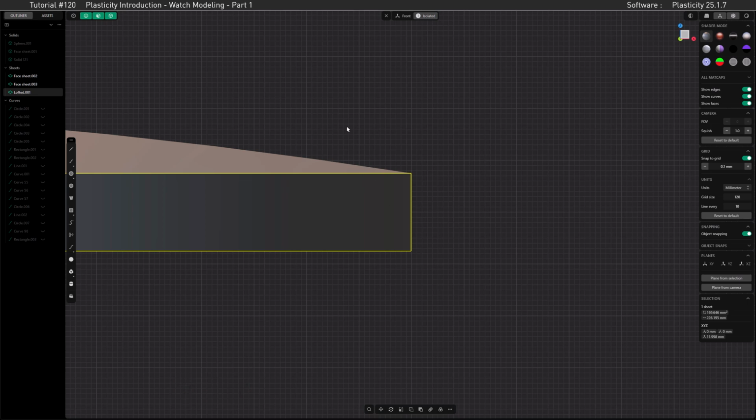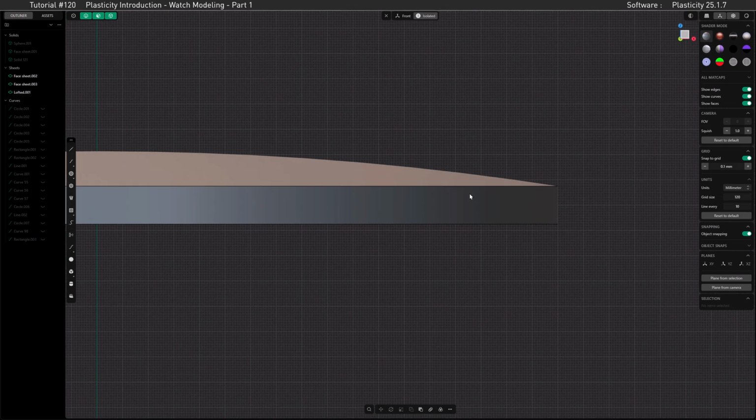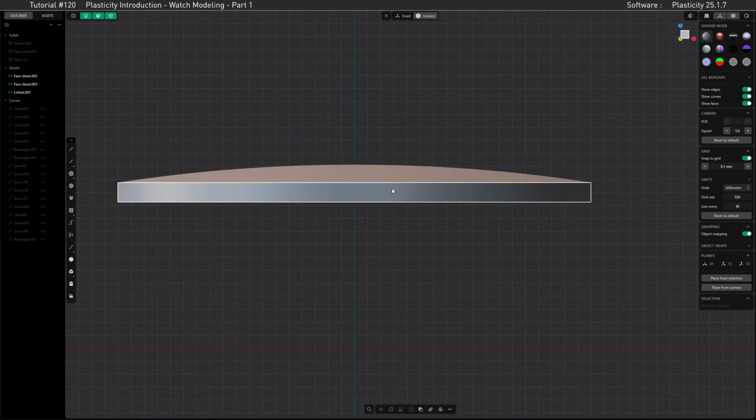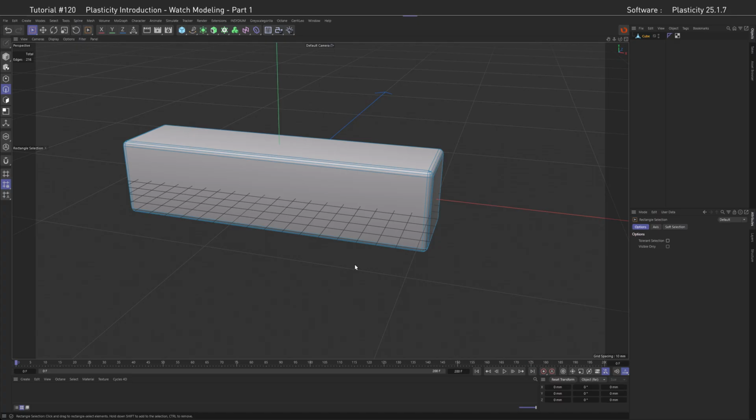And now this is a perfect time to show you something that might slip under the radar as an inconsistency while we are selecting. So if we are selecting to the left side, everything the selection touches will be completely selected. If you are selecting to the right side, nothing is selected unless it is inside the bounds of the selection completely. This is a little bit like tolerant selection in Cinema 4D, but built in the gestures of one tool, which is very elegant. At least if you know, otherwise you might be confused about the selection behavior sometimes.